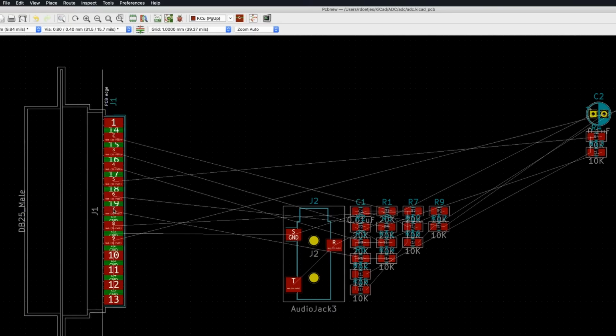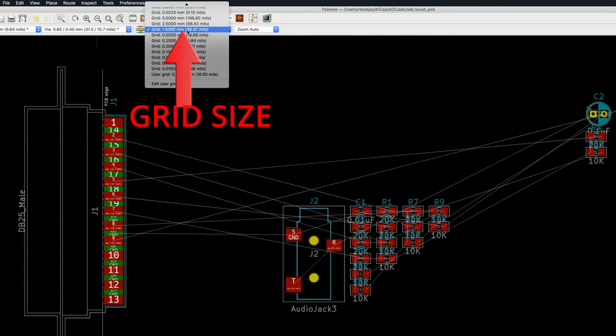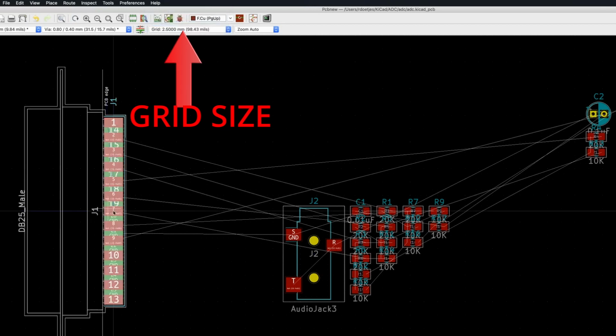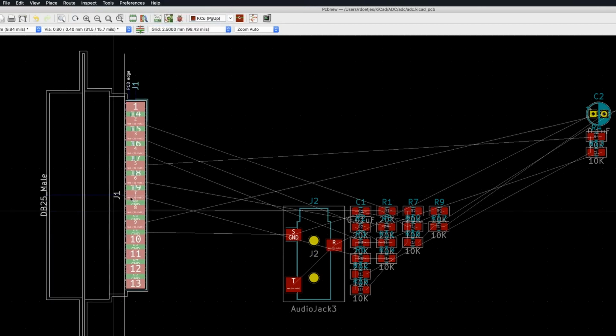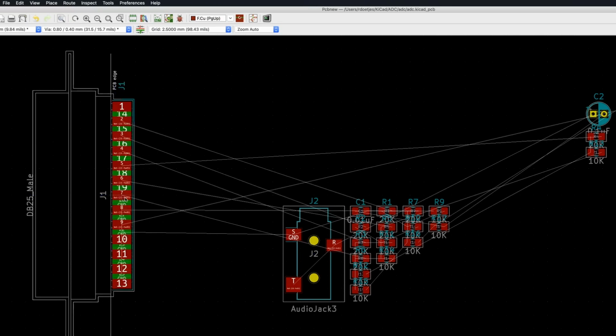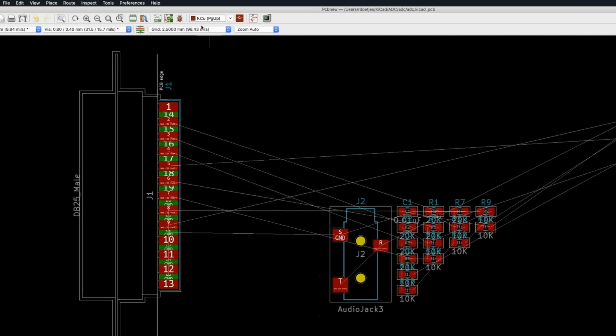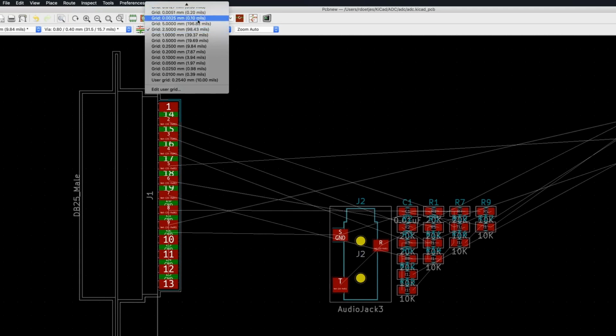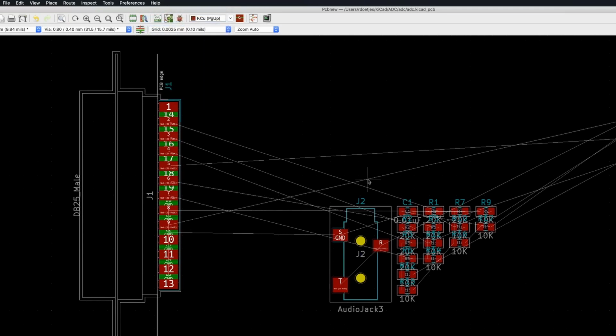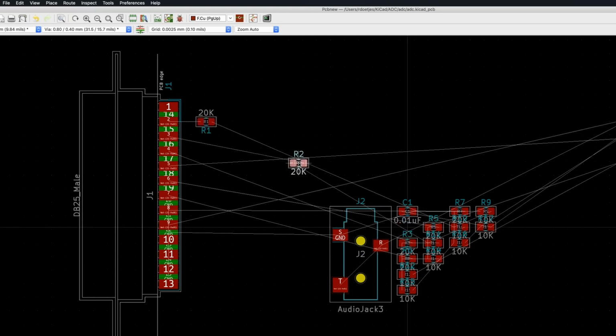So yeah. Let's set the grid to 2.5 mil. That is a European standard size. Let's put it there. Here you can set your grid size, and for the components I will generally put it on 0.25. So let's move my M1 in, click on it, M for move, and let's see how it's wired this way. R2, that's R2, move, rotate, R for rotate, it's the same key combinations.